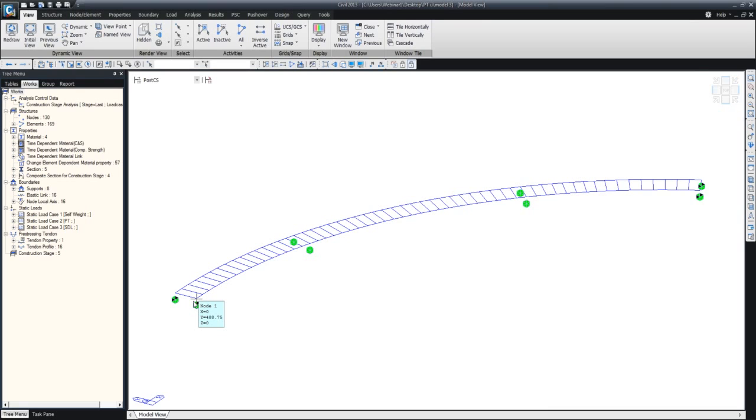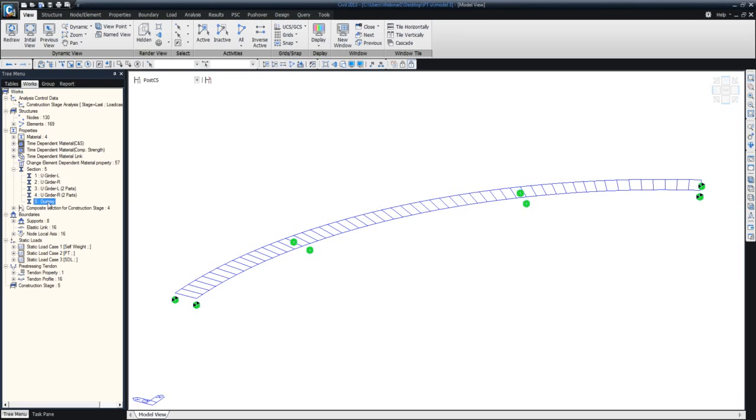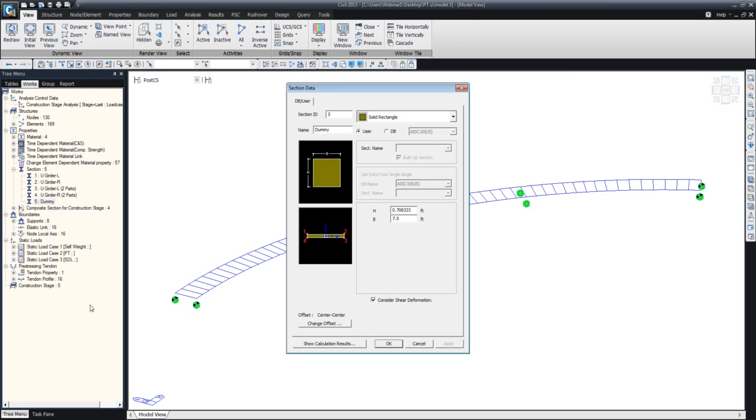And the dimensions and the section stiffness properties of these dummy members are pretty standard. There are two ways that are very commonly used. The first way that we used here is, if I right click and go into the properties, this dummy deck has the thickness equal to the deck slab thickness, and the width is equal to the spacing that we are applying here.